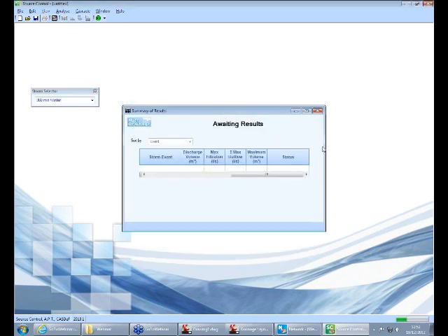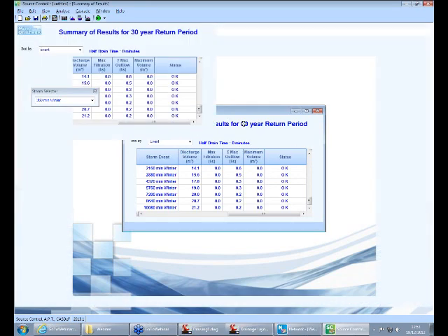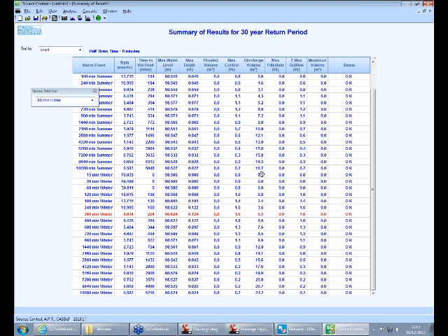So if we go OK on our time area diagram form, it then automatically updates our summary of results. And we can see what was flooding, 3.4 meters cubed, has now disappeared. This max depth before was well up above 1.5 meters, and you can see it's actually made quite a substantial difference to the depth of water in our storage structure. And it's possible if we had even a slightly larger tank, again, for rainwater harvesting, we wouldn't need a storage structure here at all.